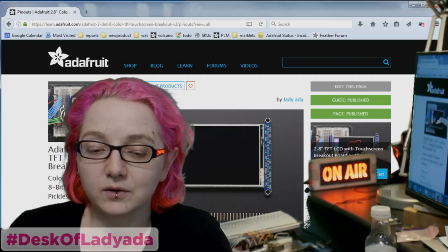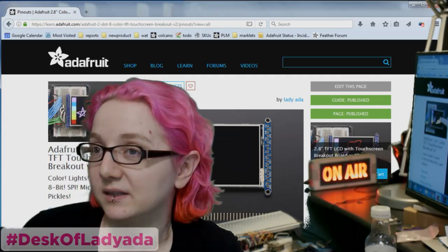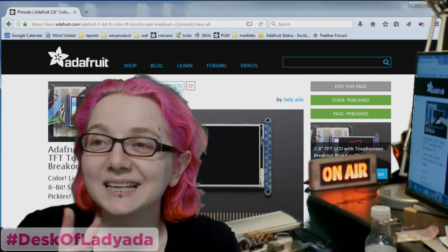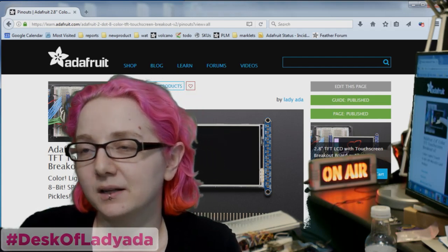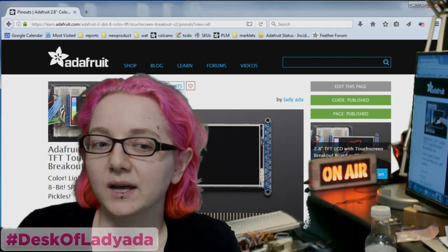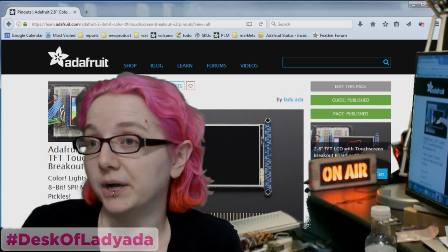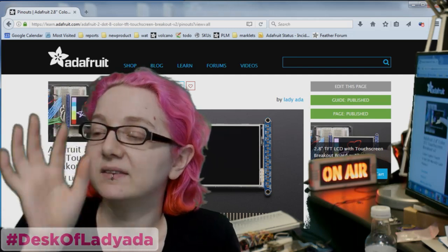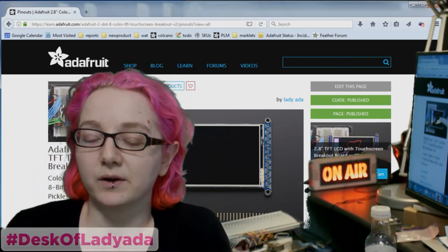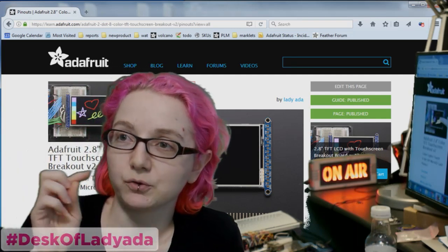Resistive touch can't do multi-touch. It technically can do 2 touches, but not very well. And I'll show how resistive touch works. Capacitive touch can do multi-point, because each sensing is done separately, whereas with resistive, you can only measure 1 point.